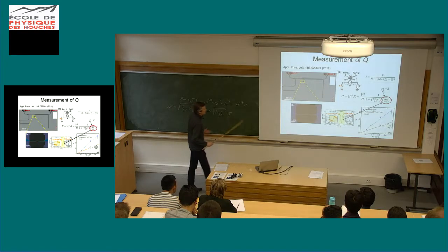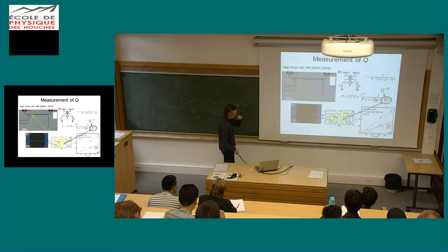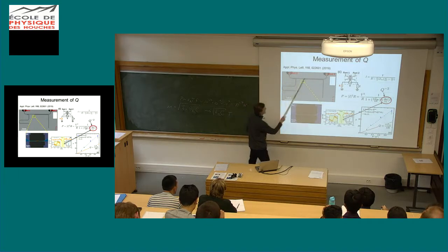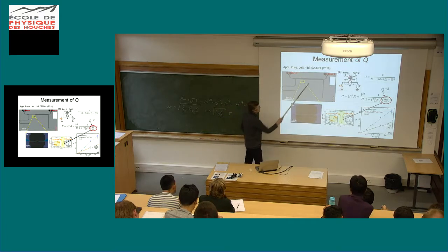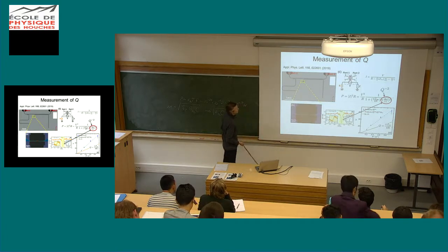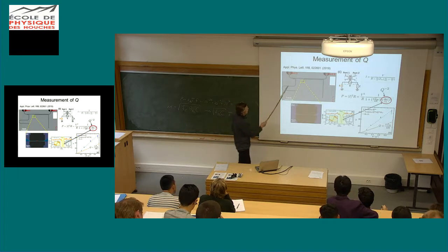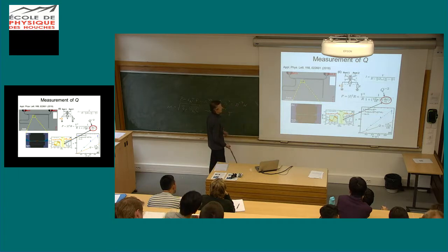Recently this is really something kind of unconventional. Usually what one measures are extremely sharp resonances. The way to measure them is to look at the transmission. I talked to you about S21 measurements: you put a signal in, measure the signal out, and look at the transmitted power. When you couple to the different resonators here, inductively in this case, you have some losses because these resonators are losing some energy at the resonance.